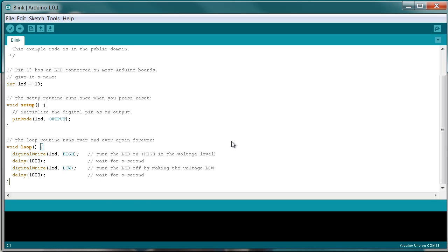So that's really simple. As you can see, the final effect that we see in the hardware is an LED blinking with a frequency of 1 hertz or 1 second that you can easily adjust by changing the values here in the delay. So that was the first basic example, and then is the first one that everybody does to check the board or to start learning a little bit of Arduino.